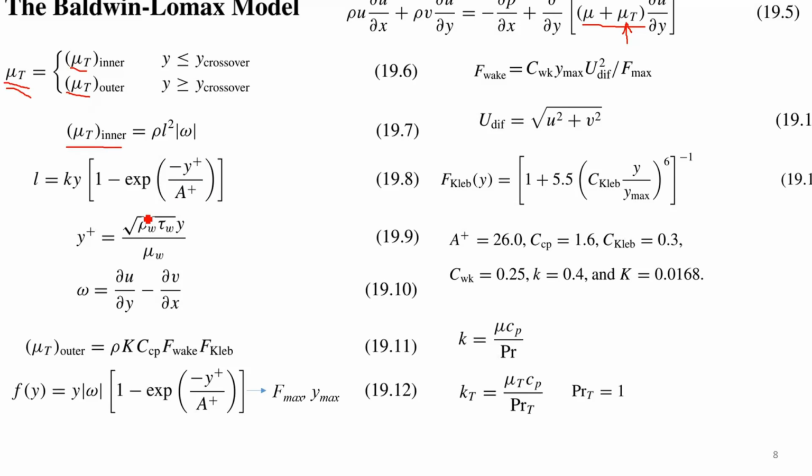Here all parameters are given. You can see also y plus is present. Y plus is an important parameter because it enters the calculation of the turbulent boundary layer. This is why we are always interested in having y plus in a certain range. Otherwise, the estimation of turbulent viscosity would be very wrong, and the boundary layer would be very thick. Probably people who simulated an airfoil with quite a high value of y plus also saw a very thick boundary layer.